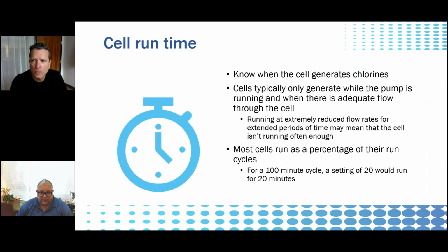Again, if you put that water bottle up to the return jet and you're not getting a chlorine residual, you know the cell's not getting the job done, that's when you look at these types of things. First and foremost, look at your cell runtime. The cell only generates chlorine when the pump is turned on. So if the pump and filter are on a timer, that means your salt cell is on a timer. Make sure that that timer is set long enough that your cell is able to run long enough to keep up with what you need for manufacturing the chlorine, right?